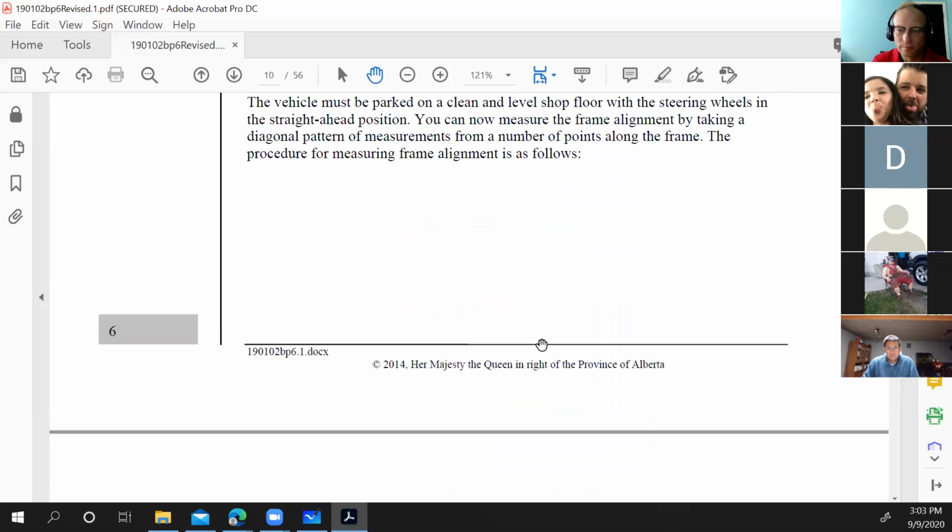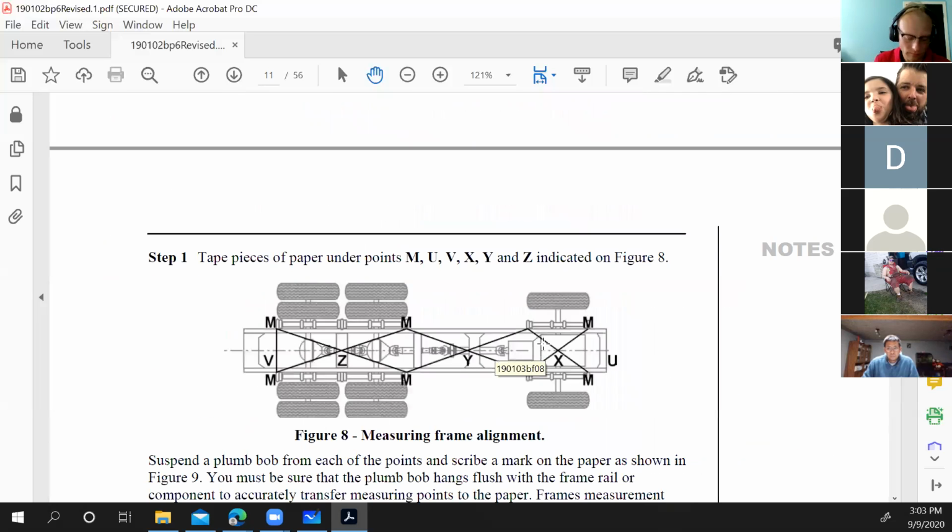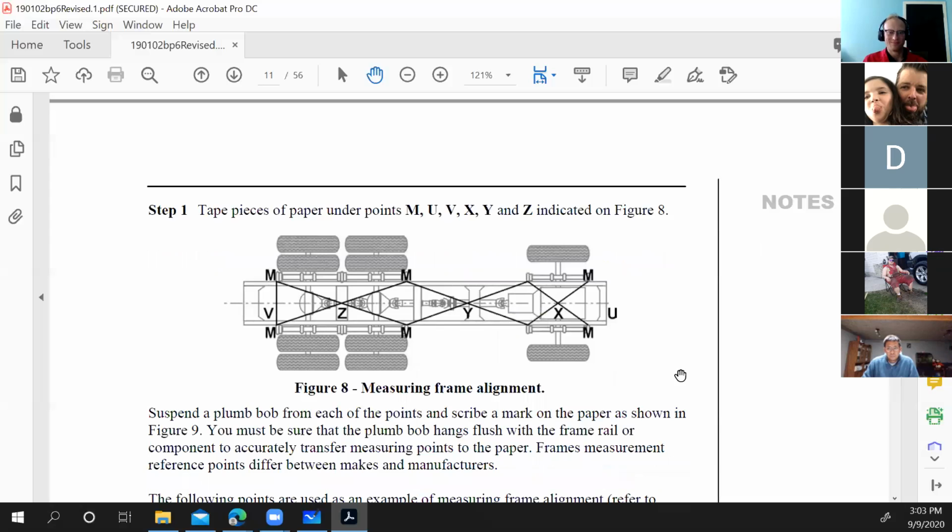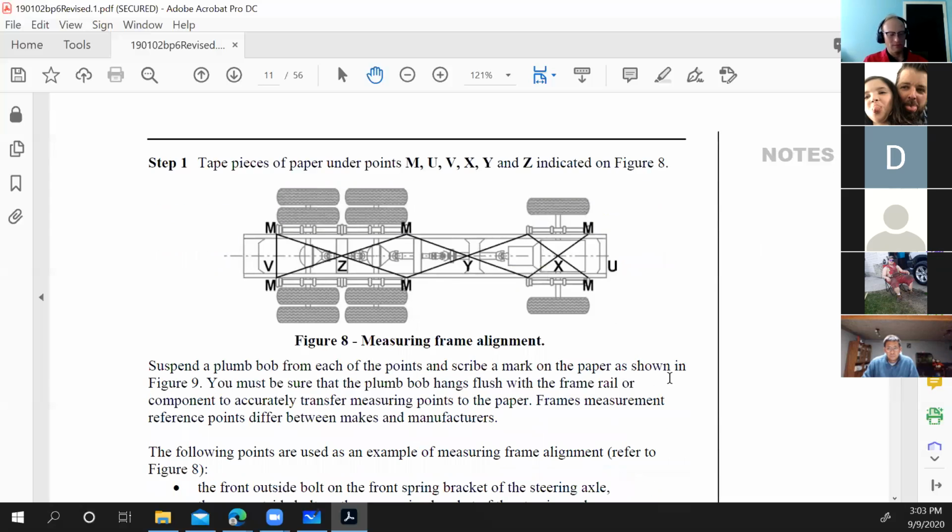Just like our 45-ton pickers, right where the picker sits and then the walking deck, there's always cracks right there, on the older ones almost every year, and it's the same crack that they weld every year. That's the maximum bending moment, the point on that truck where the most force accumulates. And obviously right where the picker attaches, you have that long arm going out and picking up loads and moving it around, dropping it off. That makes perfect sense.